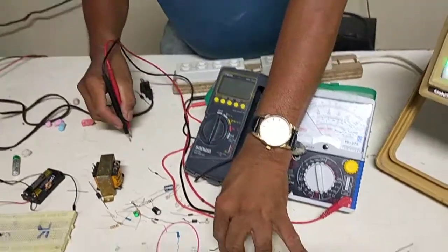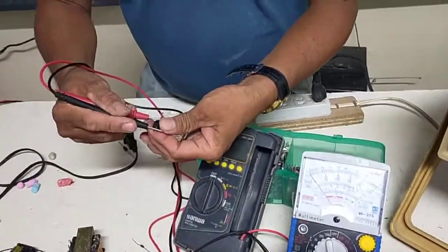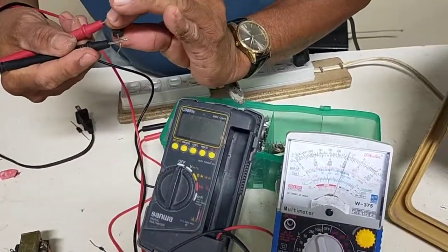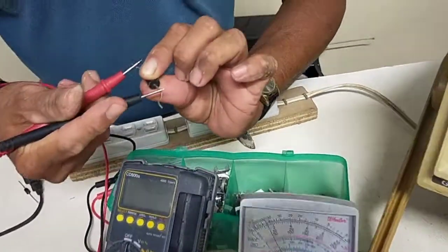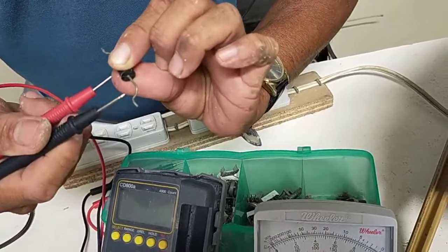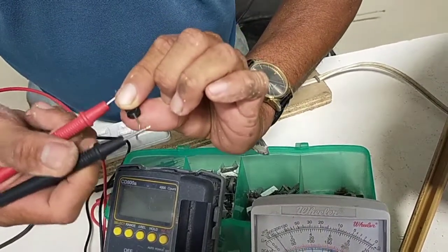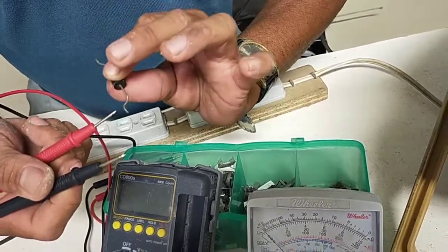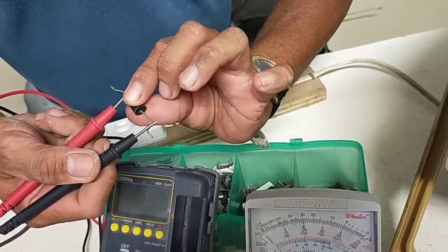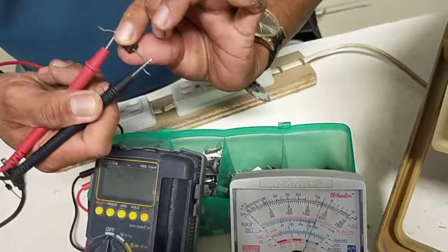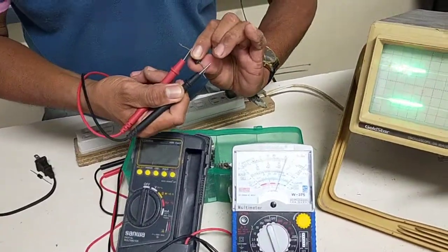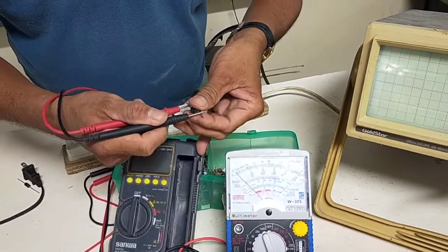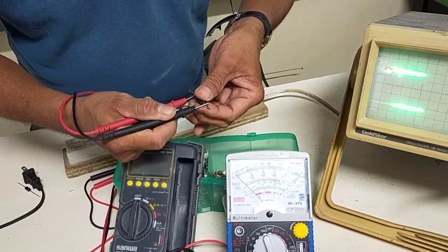when you look for the electrodes of the diode, look for the forward bias, the deflected pointer. So this is now the anode because this is positive. Anode should be positive. And this red test rod, which is negative, is connected to the cathode. So this should be the normal measurement of the diode. Deflect for forward bias, and if it doesn't deflect, it is open, reverse bias.